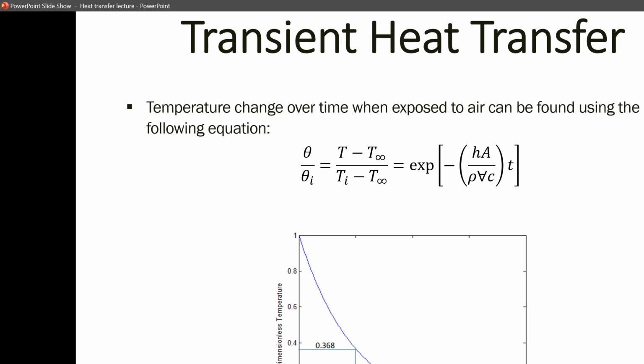So essentially, you heat up the copper block to 80 degrees, 90 degrees Celsius. You let it cool down, let's say to 50 degrees Celsius. So you have your final temperature to be 50. You have your initial temperature to be 80. Your surrounding temperature should be around 20-25 degrees. That's the temperature in the lab. You just have to record the amount of time it takes for the copper block to go from 80 to 50 degrees, which will be your time. And everything else can be measured or found from literature, which will leave you with one heat transfer coefficient parameter.